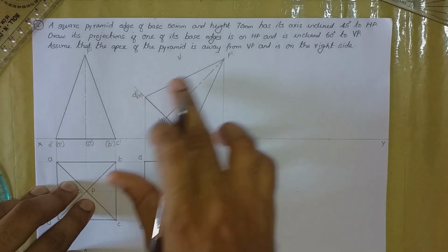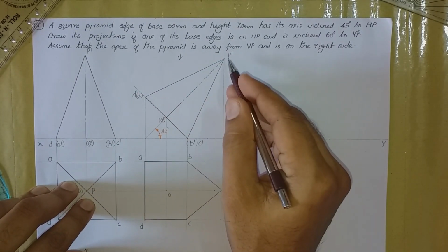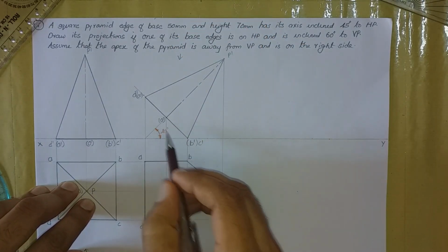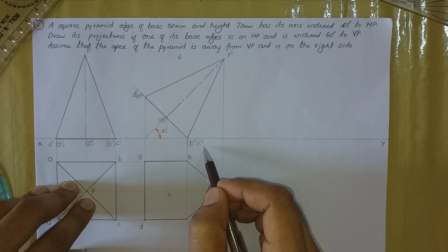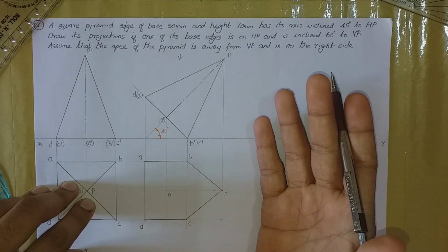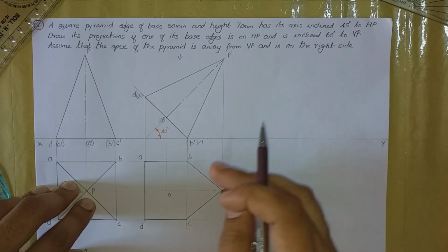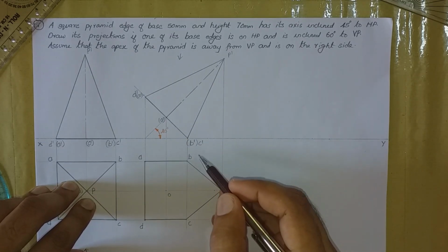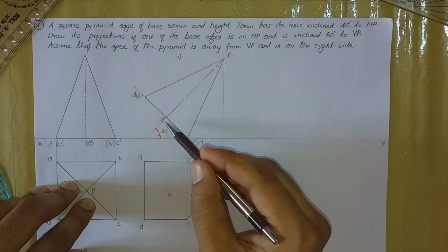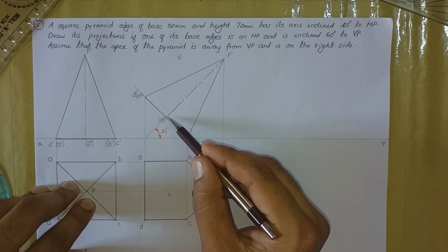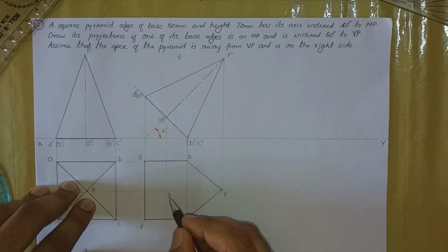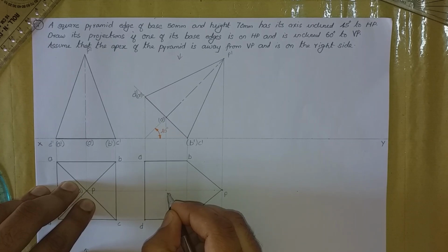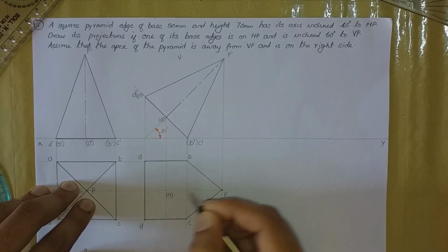So connecting these 2 points, already we are having a straight line here. So whatever is below this straight line, that is O dash, B dash and C dash, they may be invisible if they are not a part of the outline. So let us check it out one by one. O is actually the center of the base, it is not a corner, but still as it is below this particular line, we shall treat it as invisible. So we shall write it in brackets.